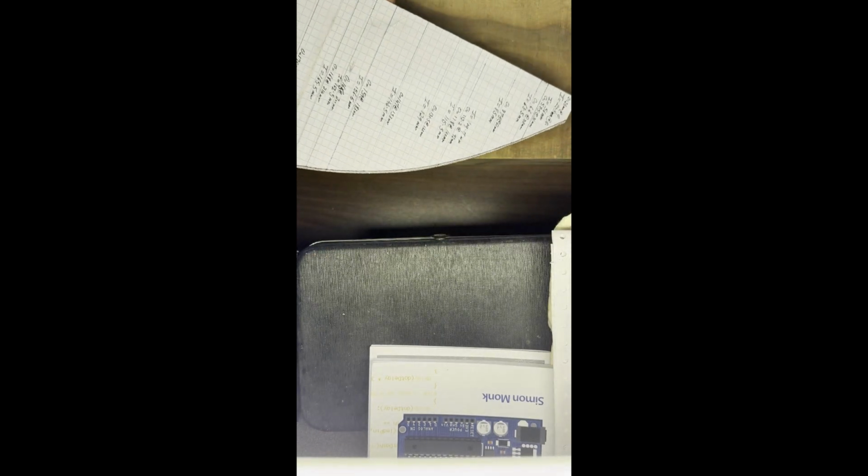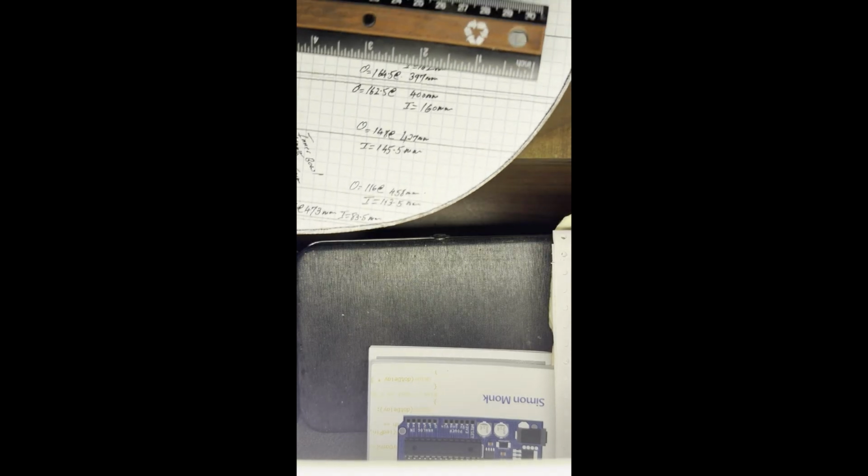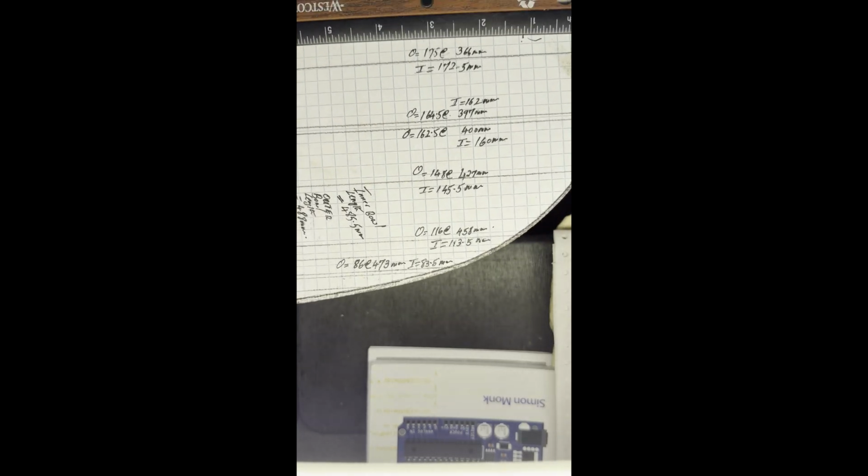So either you use the divider or the offset gauge. Divider is obviously preferred. You can use a compass, right? But after you are done marking the secondary curve, it's going to give you an approximation. In the workflow you must verify, and there are two steps in the verification. So what I do is I go back, I use a graph paper on the templates, it makes it easier, but I go back using a straight edge.